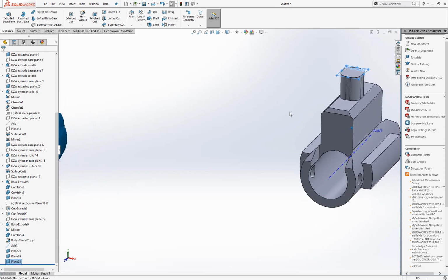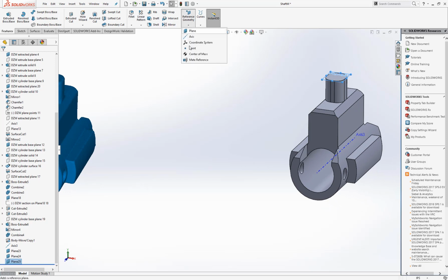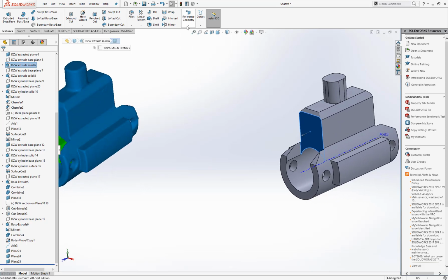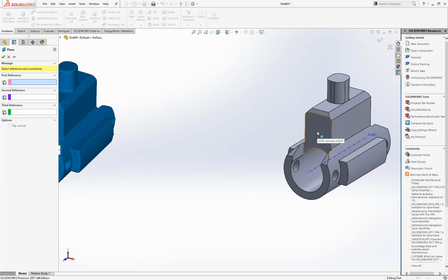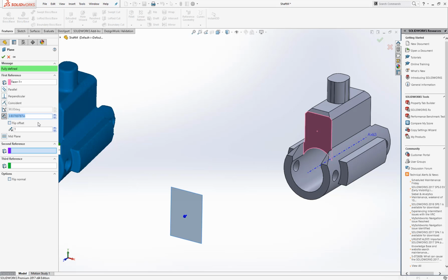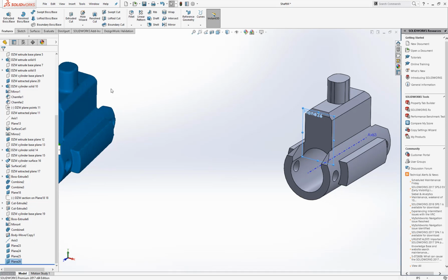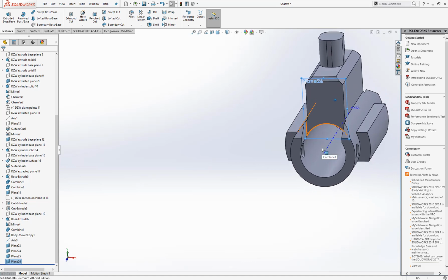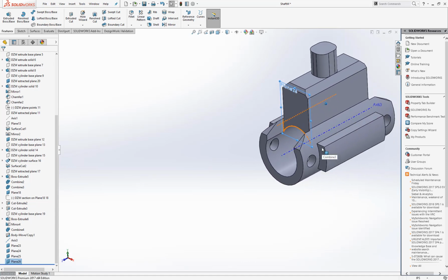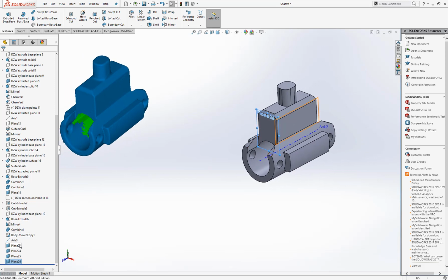We might need something to check the part going back and forth. Let's pick another reference geometry here, and we'll go ahead and actually create a plane. And we'll clear this out. Or if the callout was telling you that these were machined faces, you might be putting datums on machined faces. So we now have an axis and a few planes.